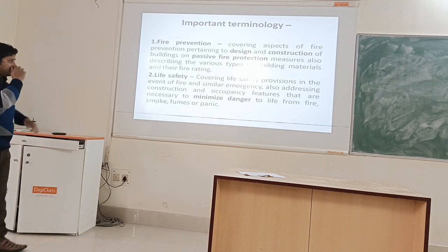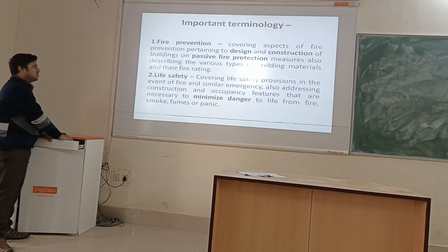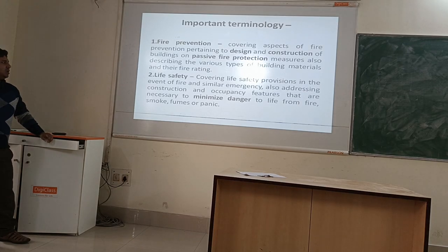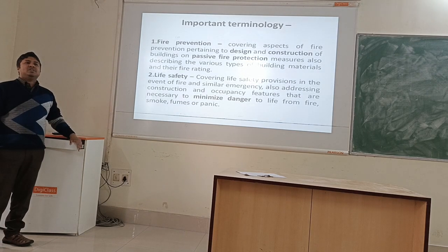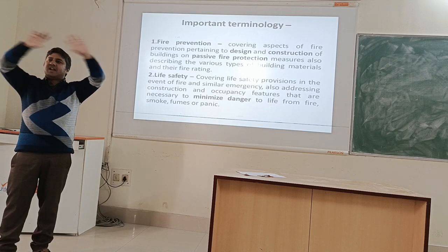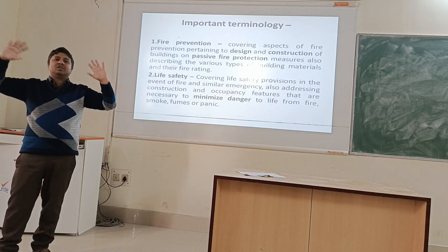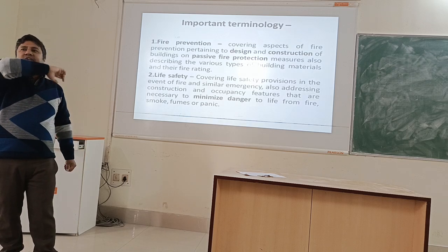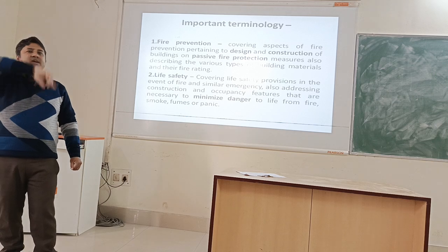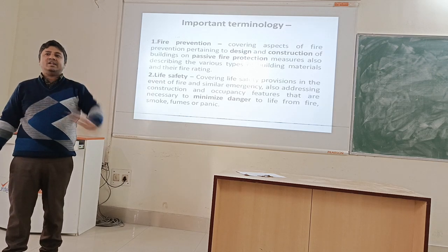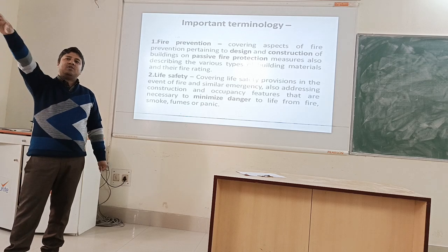So under this, the design and construction of the building should be such that any passive fire protection to be taken should be present in your planning. There will be location of fire hydrants. There will be pipelines not less than 100 mm in diameter, that should pass through every floor and be able to carry the fire hydrant pipe to the farthest side of the room.